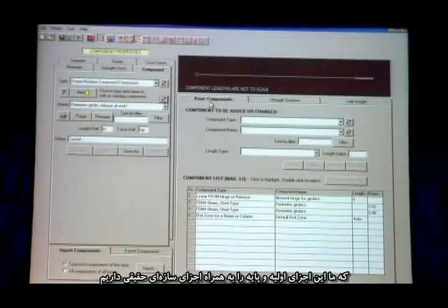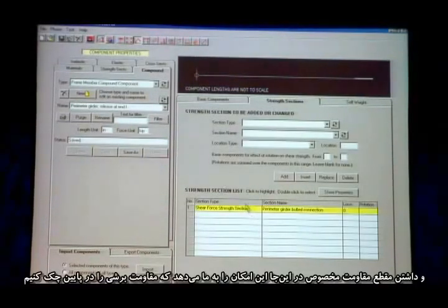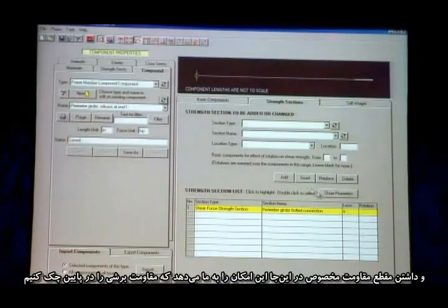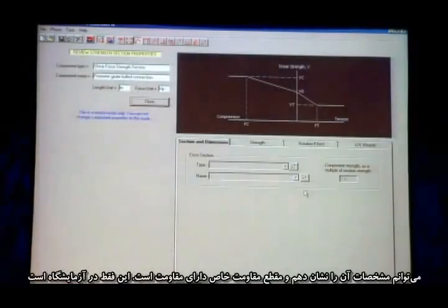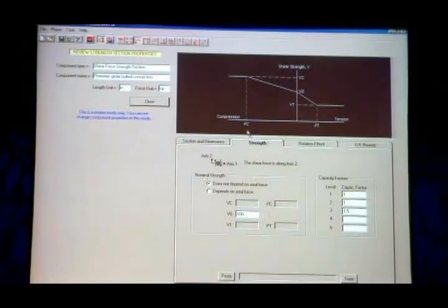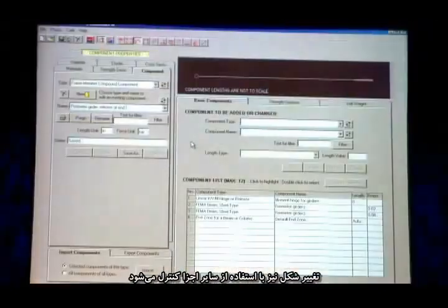And the way in which this is done is we have these basic components, which are the actual structural components, and then we have this particular strength section here, which enables us to check the shear strength at the bolts. And I can show the properties. That particular strength section has a strength of 100 kips. It's just a little arbitrary. So this is one way in a beam in which you can check the strength. The deformation would be checked using the other components.